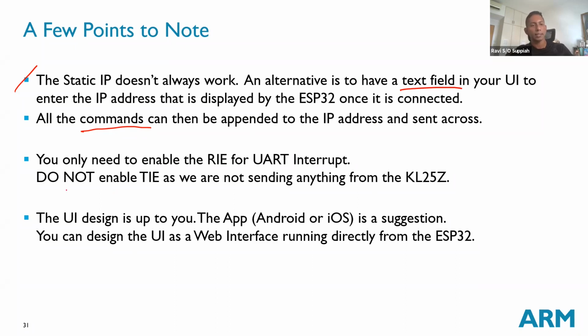Right. The next thing is the interrupt. When you want to configure interrupt, your KL25Z is only receiving the data packets. It's not sending out anything. So you only need to enable the receive interrupt. Do not enable the transmit interrupt.